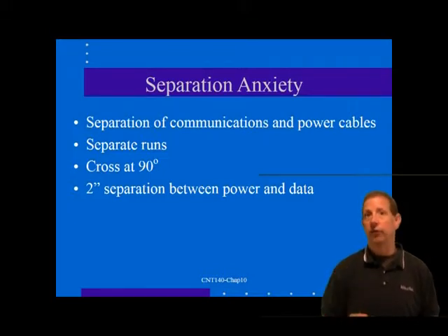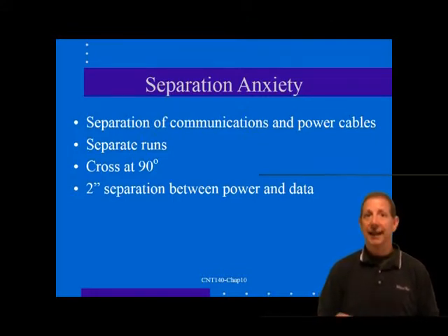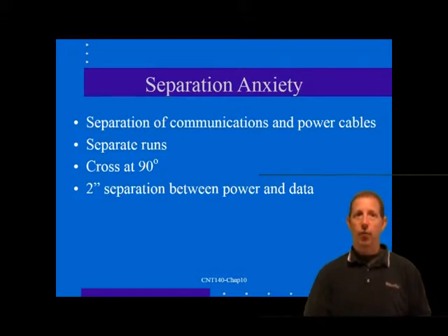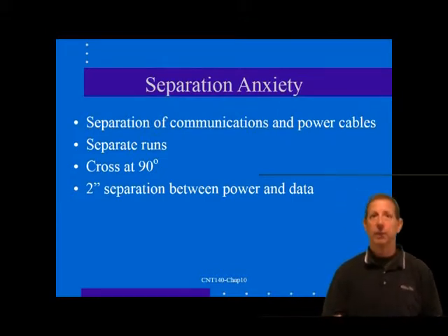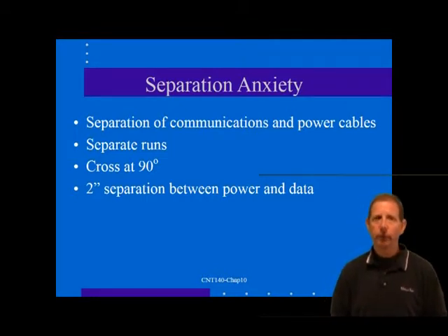The interference issue is fairly straightforward. Electrical power lines are not limited to carrying only 50 or 60 hertz electrical energy. They can, in fact, inadvertently carry interfering signals at hundreds of megahertz. In one famous case, a 243 megahertz interference signal, generated incredibly by a malfunctioning air conditioning relay, was carried hundreds of feet along power lines from the offending source.